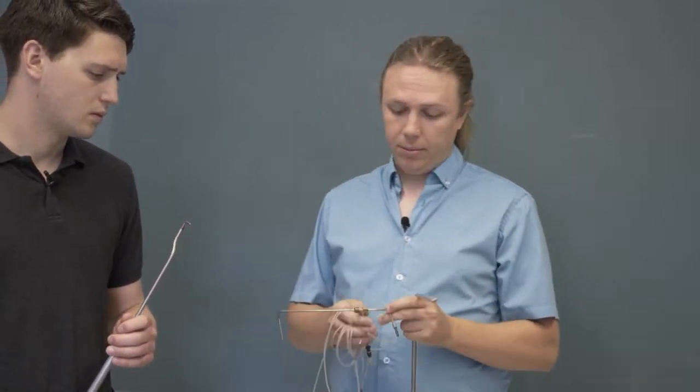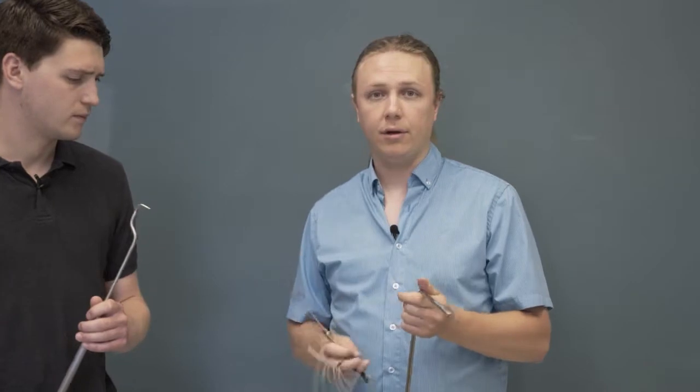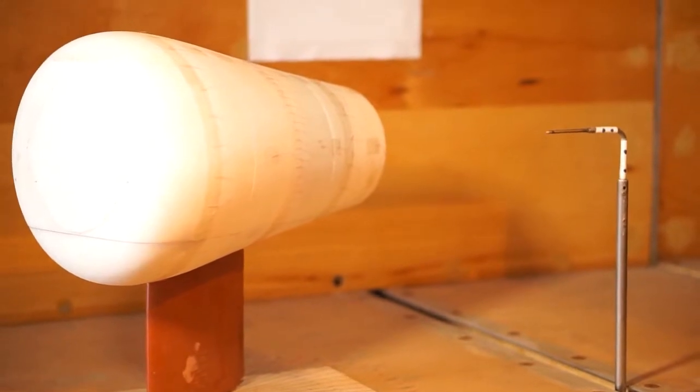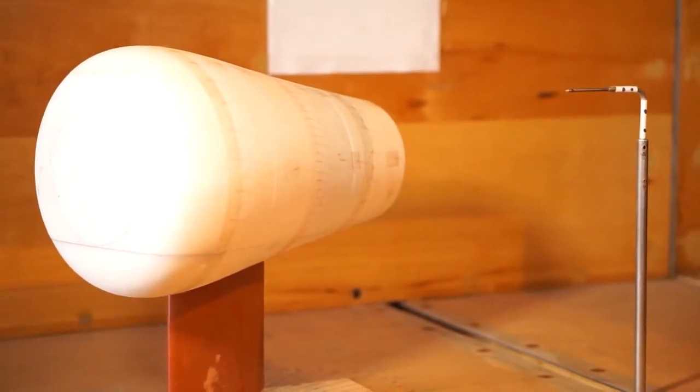So what we might do with a pitot tube is I might put one inside the wind tunnel to measure the free stream velocity of the flow, and I might put another behind a body that we're testing. Say we're measuring the drag of some body, I might put another one behind it and take a full field of measurements. So I might measure here, here, here, here, here, here, and we could describe a complete flow field or a complete contour of the wake behind a body.